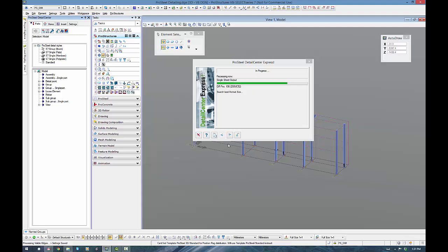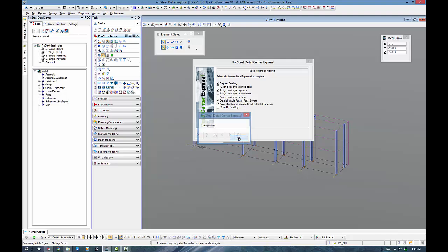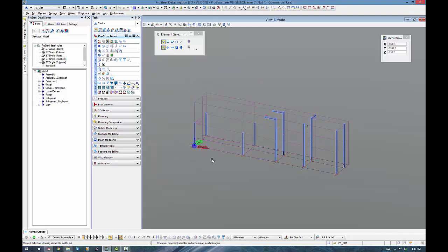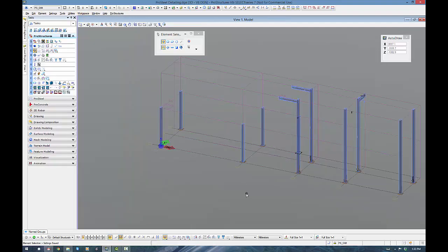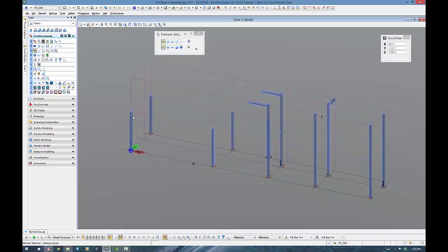Now these templates, I've given you a few in the Australian localization just to get you going. Use your common sense. If you've got a vertical object, it'll work okay with a column. If you've got a horizontal object, it'll work pretty good on the beam one, and you can build from there. But please leave the originals, okay? Just make copies of your detail styles and your templates as you go.